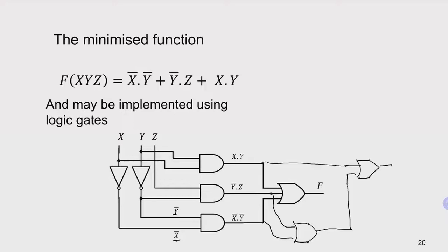So just now I was mentioning that if we don't have a 3-input OR gate, we can implement it using 2-input OR gates, using the circuit that I drew here, to implement the same function. So moving on.